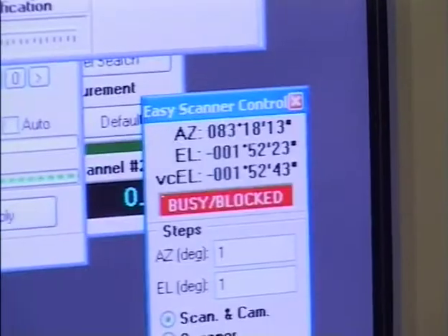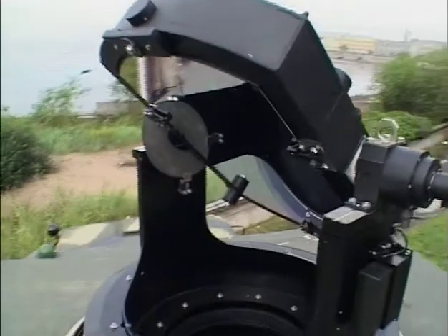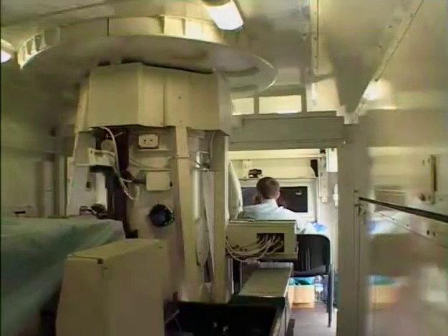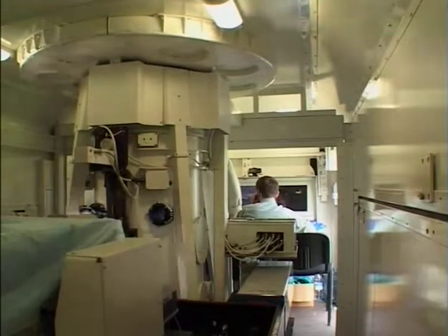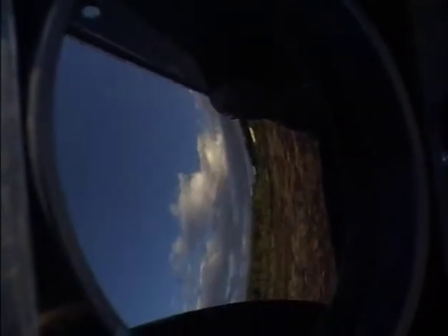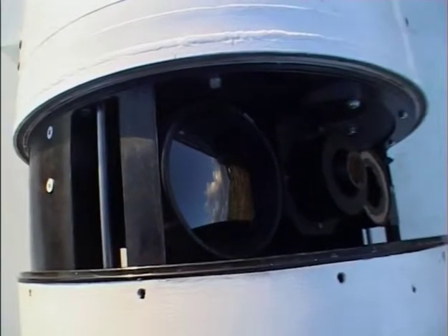The mobile LiDAR complex also incorporates a video system that allows monitoring and detecting aerosol emissions, defining aerosol cloud azimuth, as well as transmitting this information to the LiDAR system for further analysis. In order to provide video system secure operation, there is applied a special stroboscopic video camera synchronized to the radiating elements operation. While MLC3 is equipped with a single survey camera, MLC2 incorporates a number of cameras. These are wide field, narrow field, and infrared cameras combined into one independent video unit.